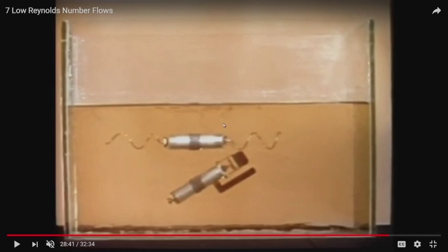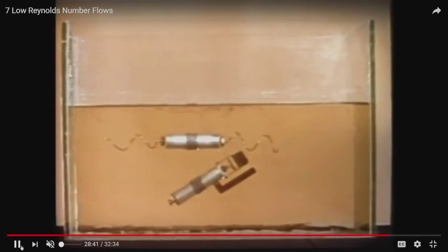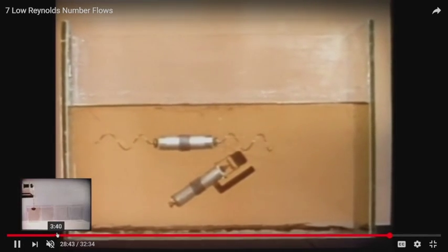Turbulent equipment will fail in laminar flow, typically. That's the standard engineering mistake, is that people have a pump, you figure it's going to work no matter what, but a pump won't work. Say it's a pump for water, it probably won't work very well if it's for very viscous molasses. So, very important point to recognize here.